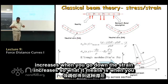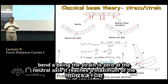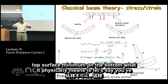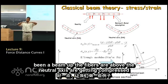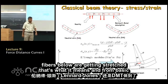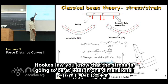So what it means is when you bend a beam, the strain is 0 at the neutral axis. It reaches a maximum on the top surface, minimum on the bottom. What it physically means is, let's say you bend a beam up, the fibers above the neutral axis are getting compressed, fibers below are getting stretched. That's what it means. And from basic Hooke's law, you know that the stress is going to be,